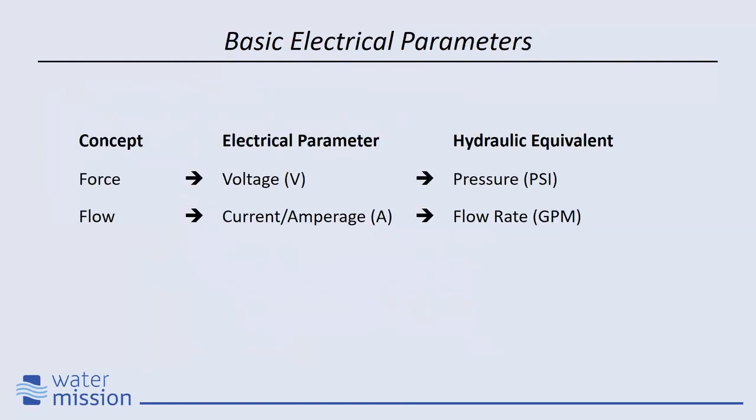So when we're thinking about how we are going to connect a multimeter in order to measure voltage, you want to think, what is voltage similar to in water? It's like measuring pressure. How do you measure pressure? You measure pressure using a pressure gauge that is in parallel with the thing that you want to see. And another thing to think about is that you're always measuring pressure differential, right? Same thing with voltage. You're always measuring a voltage differential.